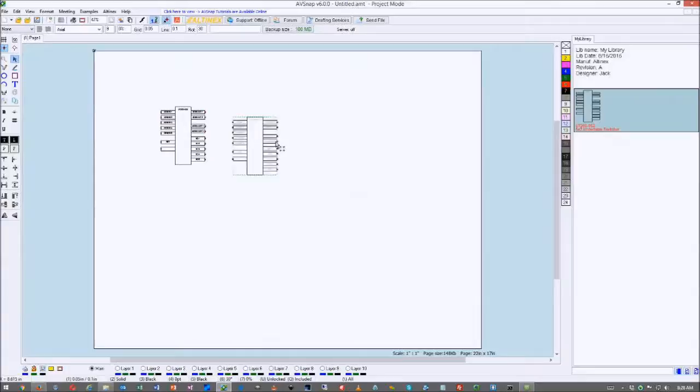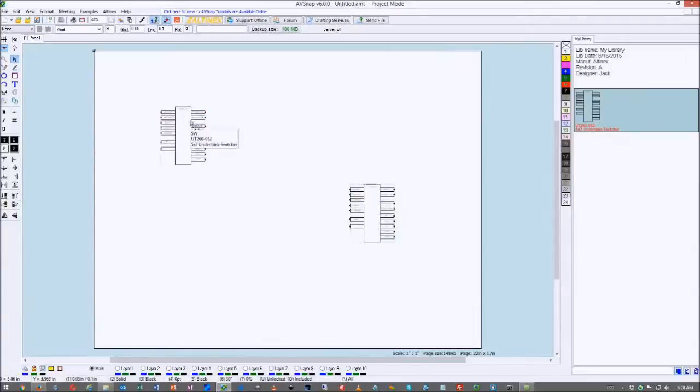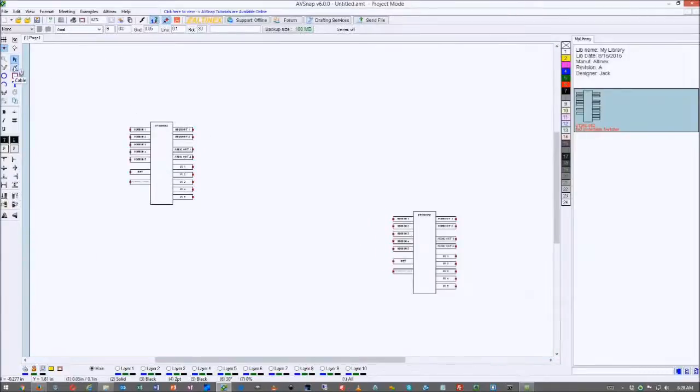Let's do some connections, some wiring connections, so we can see how it's going to look from the wire diagram. So I'm going to take a cable and just going to run it from here. As you can see, I'm going to turn my Draw Assist on. And you can see there's a line that goes between, and it automatically tries to snap to the point. So I'm going to move it to the output here. I'm going to drag it to the HDMI input here, and I'm going to let it go. I don't have to go directly to the point. Just let it go. It will automatically connect it. So I'm going to take HD output 1 and go to here, and just going to let it go.